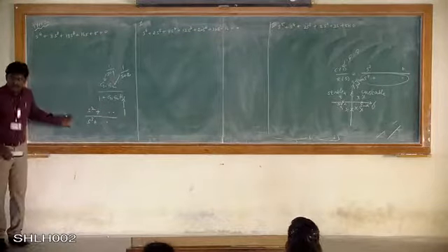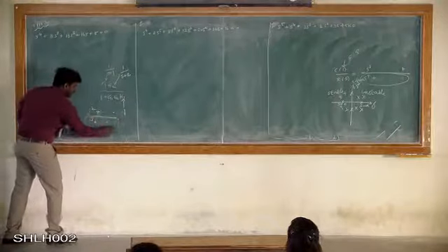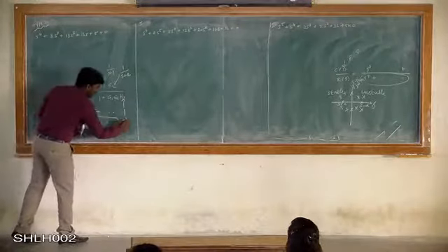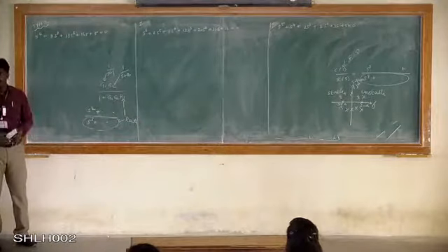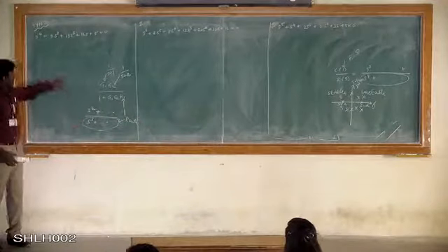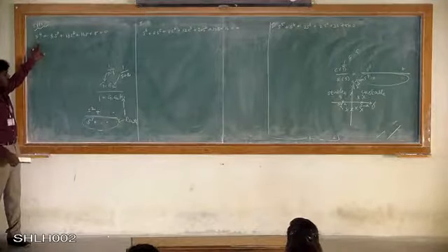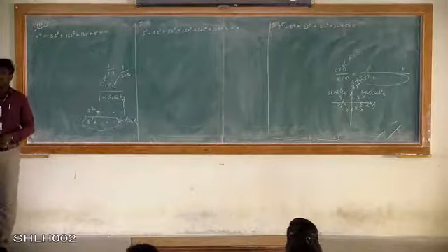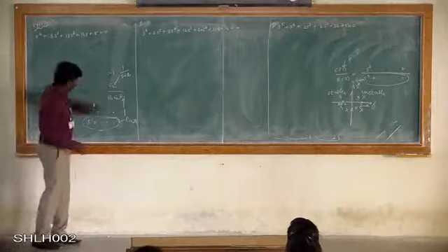In this overall transfer function of the system, you can take the denominator equation alone and apply the Routh-Hurwitz method. Okay, so this equation only I have. For some other system, that equation I have written over here, and we will have to check the stability of the system using the Routh-Hurwitz method. Okay.